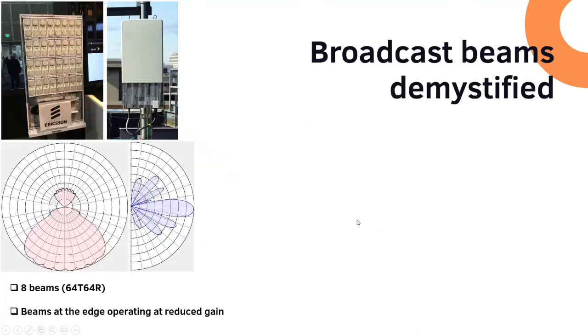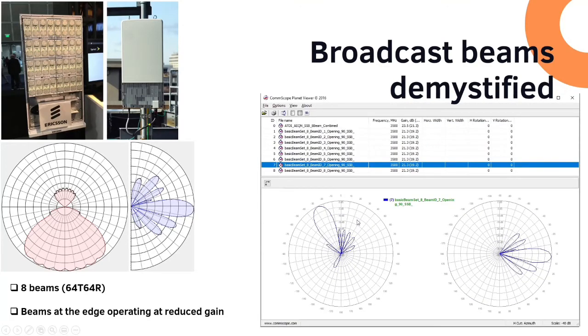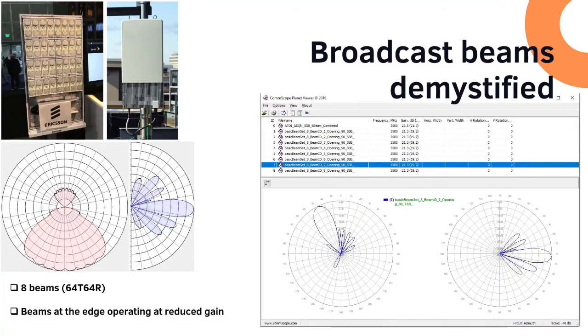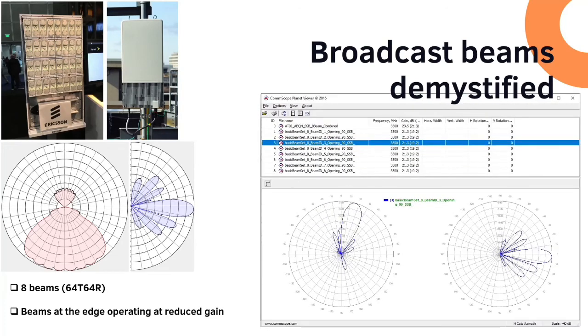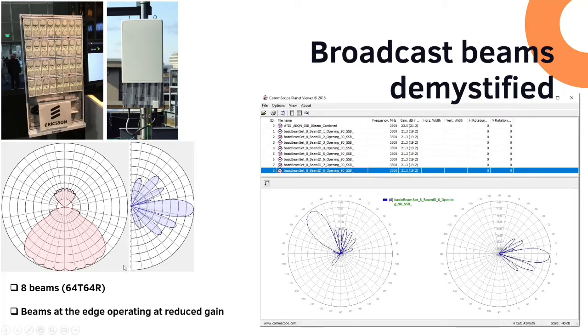I'm not going to talk too much about beamforming antennas, but this is how beamforming is working. Okay, so you have individual beams running like this. The base station is alternating the beams. So what we do, instead of modeling a single beam, we superimpose all these individual beams and we create a composite beam like that one you see on the left hand side. So we combine these individual beams to produce something which is describing the worst case scenario.